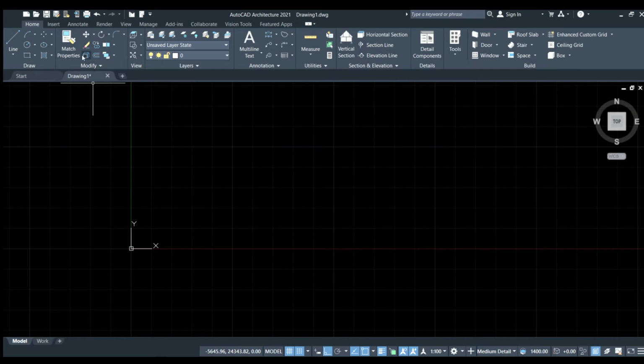Coming forward, it will be modify. Let me give you an example. When you start hand drafting on any sheet with your pencil, you always do the light drafting so that if you want to modify it later, if you want to erase it or add some entities to it, you will be able to do it easily. Similarly, this is the modify tool, which will let you copy items, erase items, move items, and whatnot, which we'll discuss further.